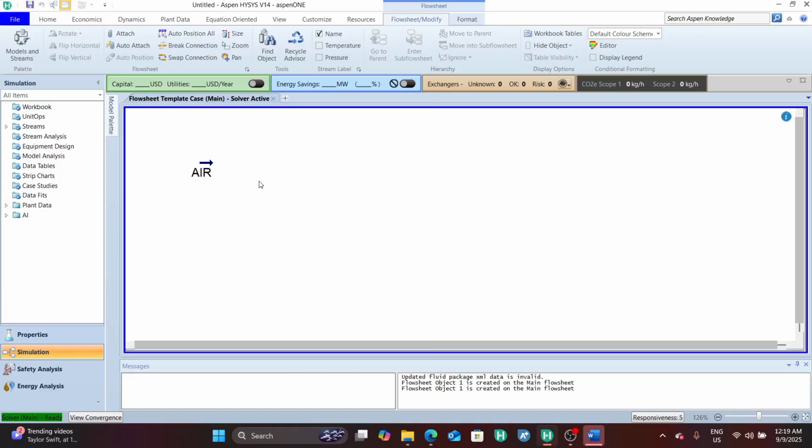Now that's a very, very low temperature, and we need to compress. At the moment we compress, we expect our temperature to go up, and that's why we have intercooling in between to drop that temperature, because we need a very cold temperature and, at the same time, an increase in pressure. So that's why they go hand in hand. When you carry out compression, you immediately carry out intercooling to control these operations and conditions to fulfill your criteria for going inside the distillation column.